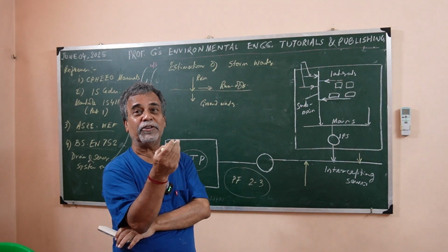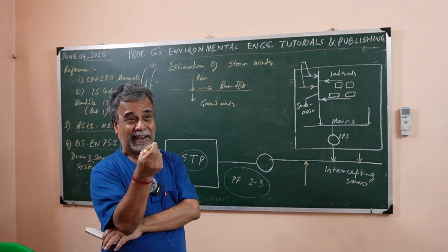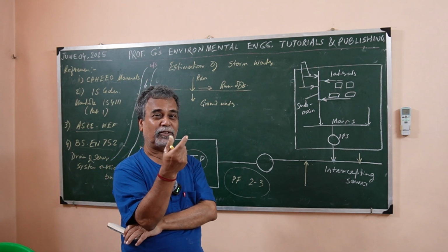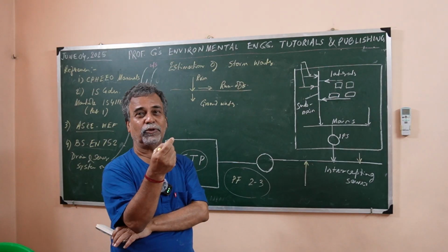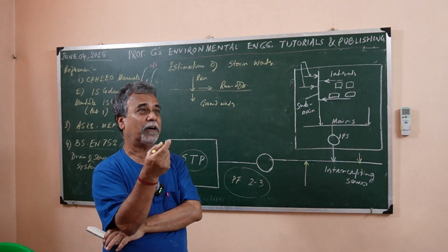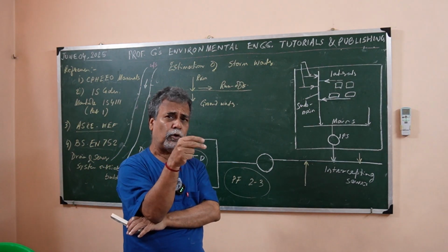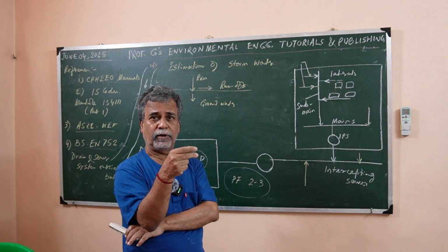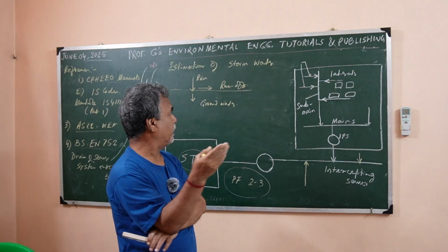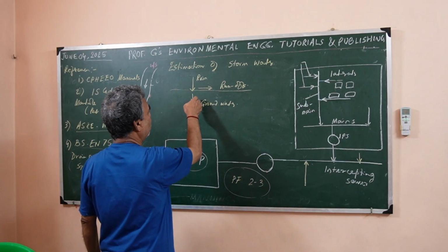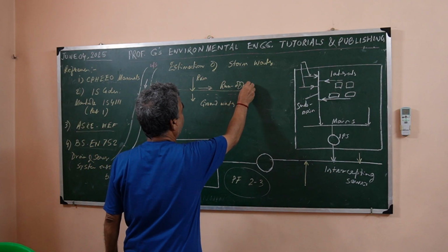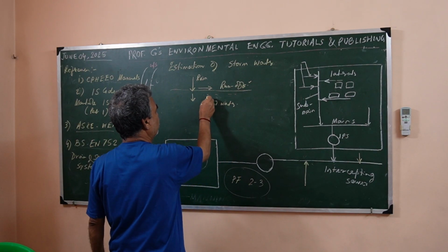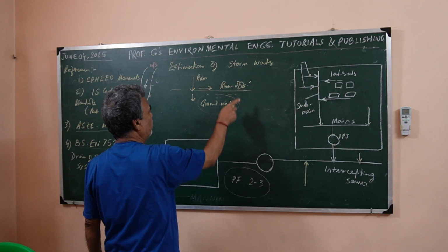So for hard soil also, where the clay content is more, as you know from soil mechanics, the percolation or penetration through soil will be less than the clay. So depending on the soil characteristics, runoff will be decided, and similarly the groundwater flow, how much that would be decided.